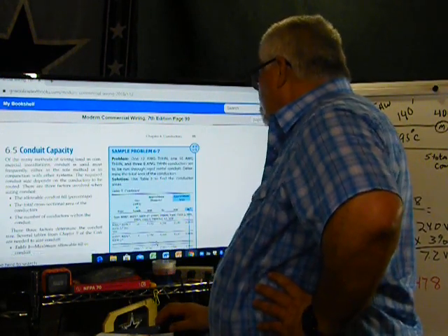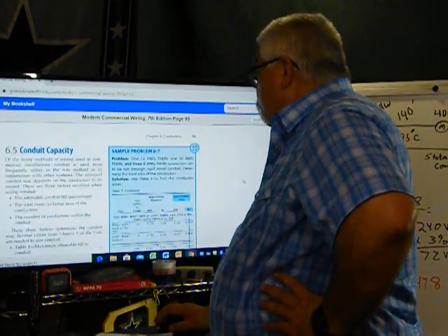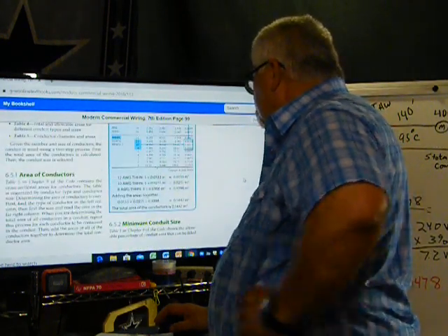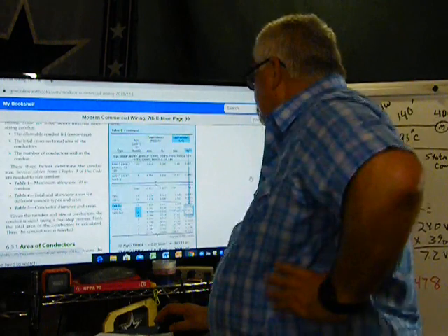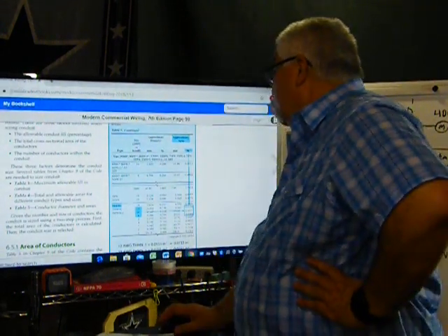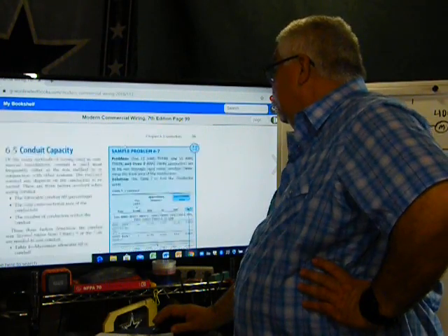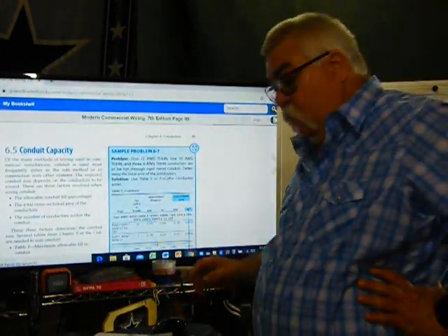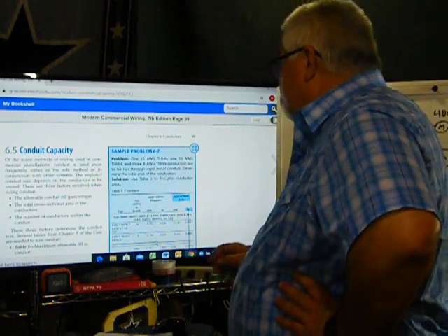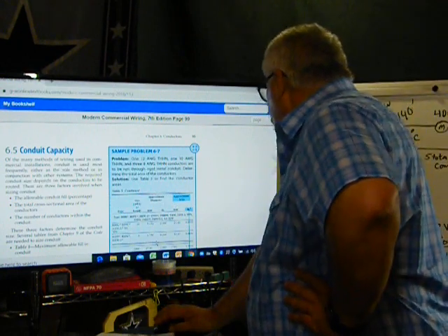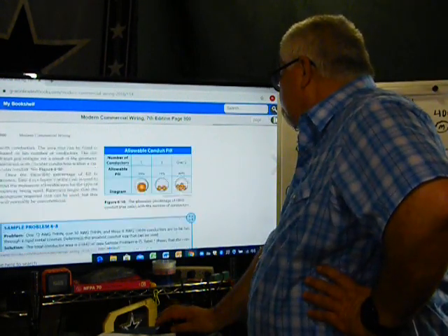Again, the next one is conduit capacity. Wires that you can get in a conduit. Okay. So in order to find the wire size, we need to use Table 5. Chapter 9, Table 5. You had it in one of the handouts. Part of it is here, and some of you have the ugly, so you can find it in your uglies.